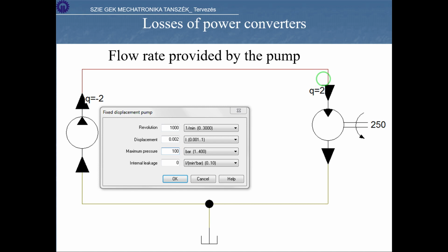But first things first, we will look at the pumps, how the pumps can be achieved, and we will use one type of them. But first, here is the pump symbol. It's fairly easy because we saw that in pneumatics. It was the compressor, where the triangle was white, but in hydraulics we show that it's a hydraulic pump by the triangle being black altogether.